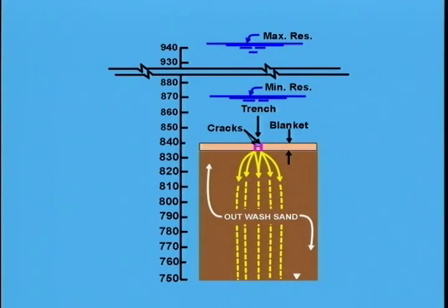Under the 100-foot water load imposed upon it, the blanket settled. Due to the glaciation which occurred at the site, the foundation had linear features of higher and lower compressibility material. Thus, the settlement pattern which developed had ridges and valleys. As at the Tabella blanket, tension cracks developed along the ridges. At both projects, the tension cracks developed first at the crests of the ridges. They then readily penetrated through the blanket by hydraulic fracturing. The reservoir pressure, which entered the initial shallow crack, was definitely greater than the horizontal earth pressure in the blanket. Because of this unbalance in pressures, the crack readily penetrated to the bottom of the blanket.